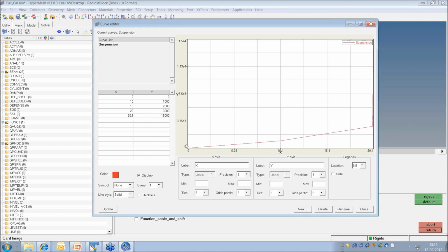So here what I'm doing is I have created a ramp. My intention is, I know my spring locks after say 20 mm. A suspension will have a behavior where after moving a certain amount of displacement it will lock. So this is something very similar, and I'm trying to do it here. Till 20 mm it moved, and after that normally this is not the value we give.